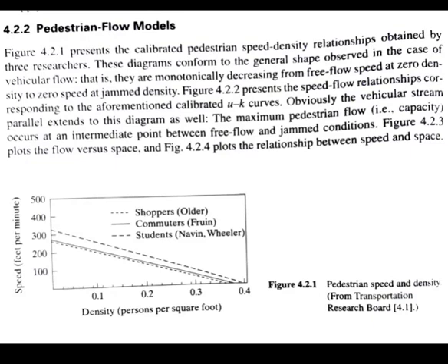So the chances of the flow getting stopped at a particular point is very common in interrupted flow. So mathematical formulations usually yield capacity in units per hour, normally vehicles per hour, and one or more measures of effectiveness such as speed, density or delay.